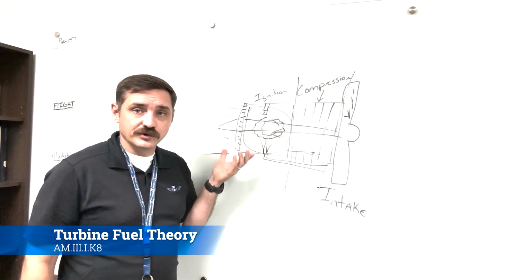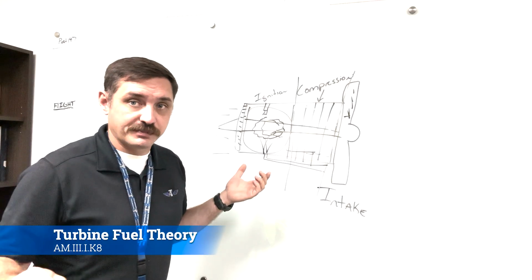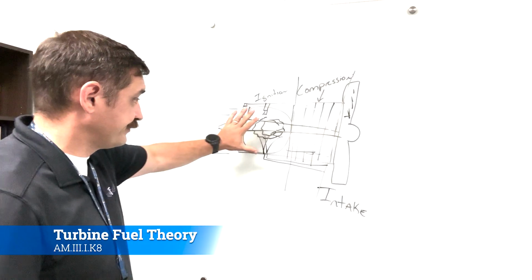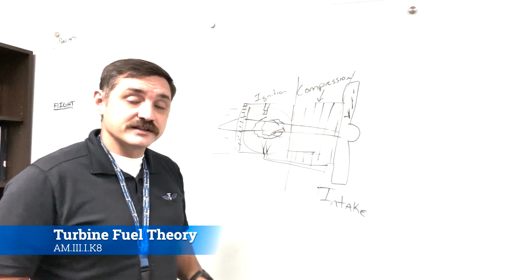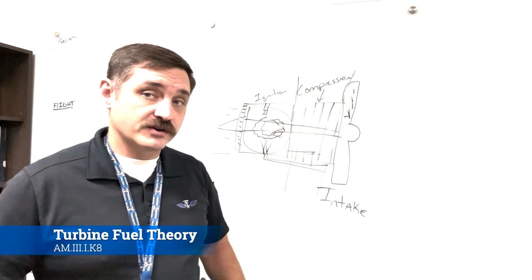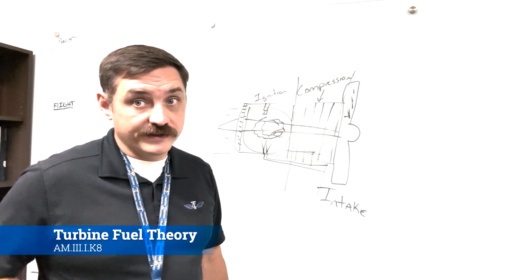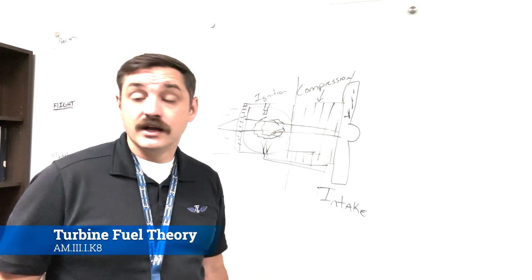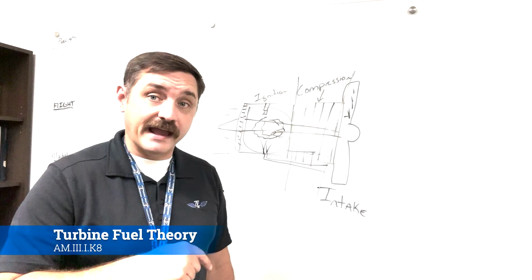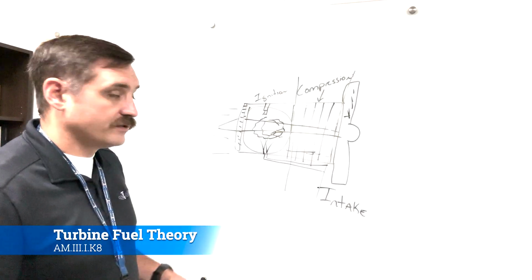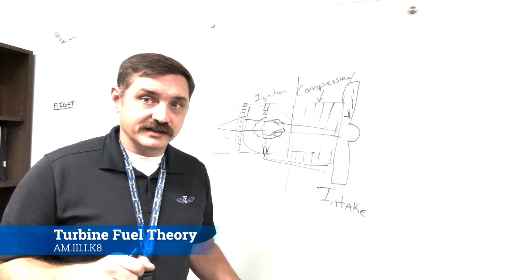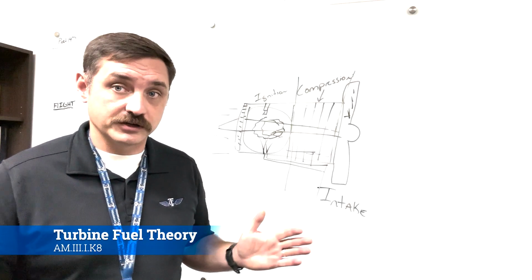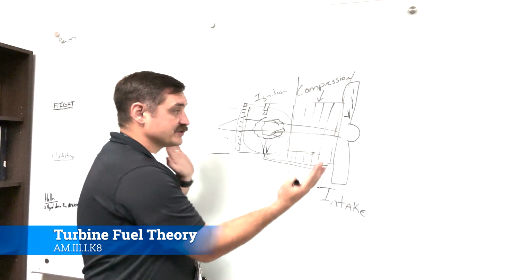As we introduce fuel, then we'll introduce a spark. A lot of times that happens simultaneously depending on the configuration of the aircraft. Boom, boom, boom. And so you can see there's a human element in here that you can hot start an engine. You can give it too much fuel and then it lights off with a big flame and does all kinds of damage to the engine. You can also do a hung start where you don't have enough gas in there. All right. So there's always the dude in the cockpit that's making these decisions. And that's going to play into when we start talking about FADEC and hydromechanical here in just a minute. But so that is what is happening.